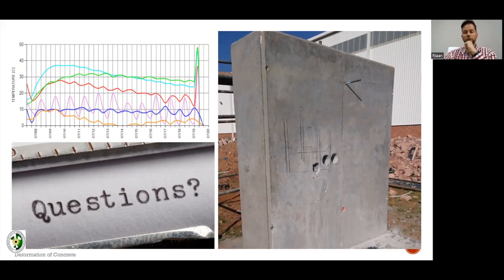And you remember that shrinkage and creep is related to your paste. So it's a moisture dependent thing. And if you have a lot of moisture in your concrete, that moisture wants to get out at some point. So if it settles and bleeds and you didn't recompact your concrete, you end up with a lot of capillary pores that actually causes you to have porous concrete. Concrete becomes almost like a sponge, where it will want to suck water continuously, or anything else for that matter. If it can take water, it will take CO2 also.